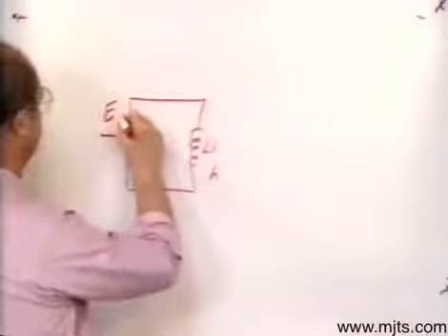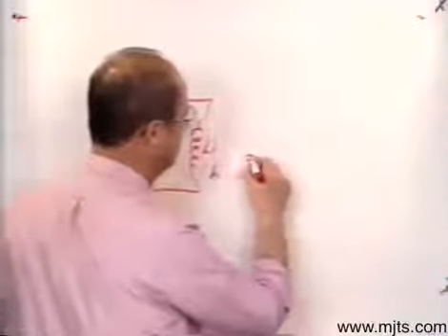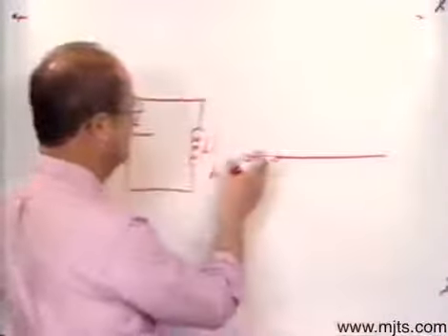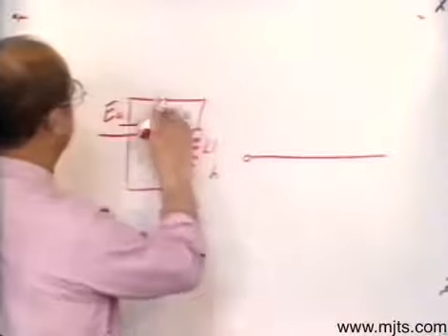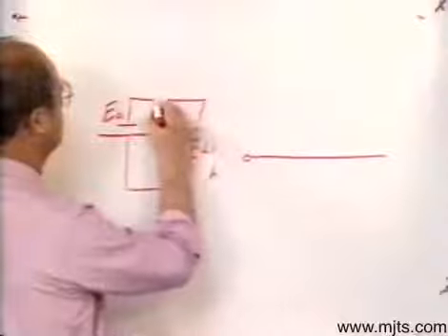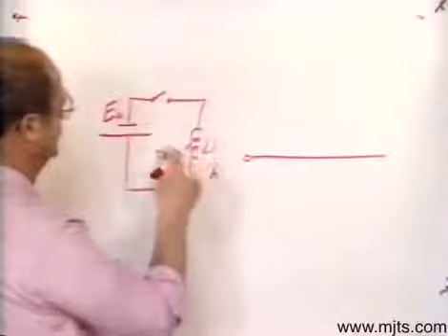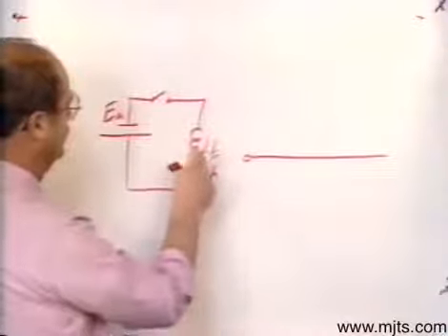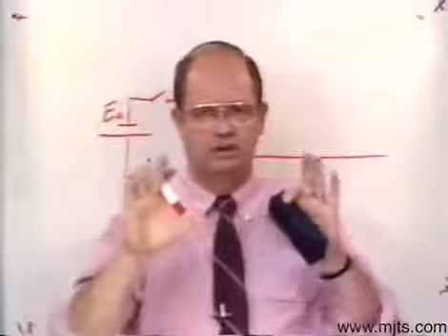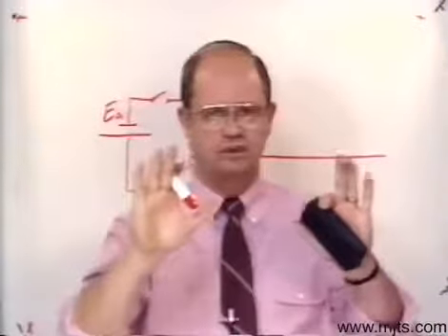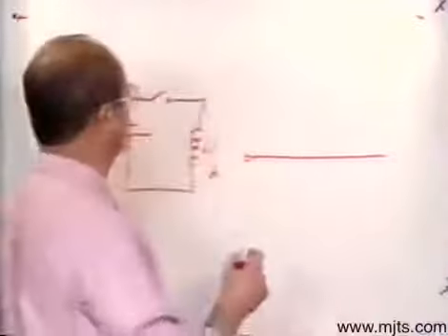We have an applied voltage onto this circuit. Now here's the thing that's important to remember. If I draw, say, a level line here for zero current flow, like I did for that resistor, and we're going to put a switch in this circuit just like we did for that resistor, and when we close that switch, we said that the opposition to current flow created by that coil in that circuit was going to cause a counter electromotive force, which in turn is going to hold back our current flow. In other words, it opposes a change in the current flow.